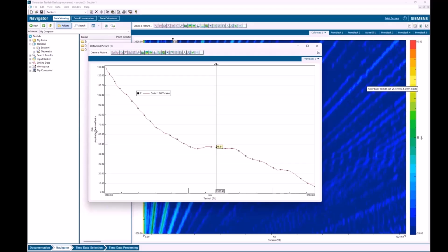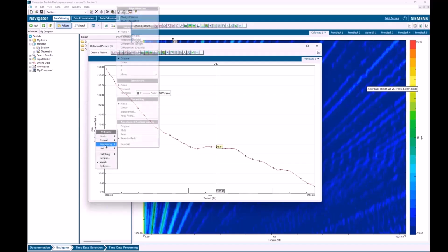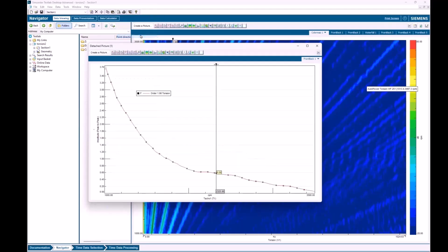That's just an integration. So if I go to processing here and I pick integrate, notice it just changed that to degrees, Charles. Yep. And I have done peak to peak. This is fluctuating plus or minus 0.58 degrees total at this RPM. At these lower speeds, I'm getting up to like 3 degrees of total deflection in my shaft.